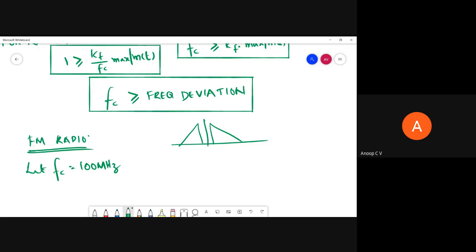It will have frequency content from 300 hertz to some 15 kilohertz. This is our message signal and its spectrum M of F. The maximum frequency FM, or W, is equal to 15 kilohertz.